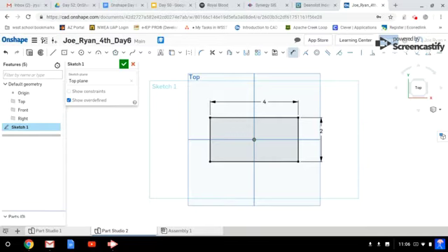Okay. Also, iPhones don't have sharp corners on them. So I need to take care of these corners. To do that, I'm going to come up here to this Sketch Fillets button. So I'm going to click on that. And then I'm going to click on the corners of my sketch. And I'm going to click again to confirm. Press enter. Click here. It's asking me, do I want my radius to be 0.5 inches? Yeah, that's fine. I'm going to click again.